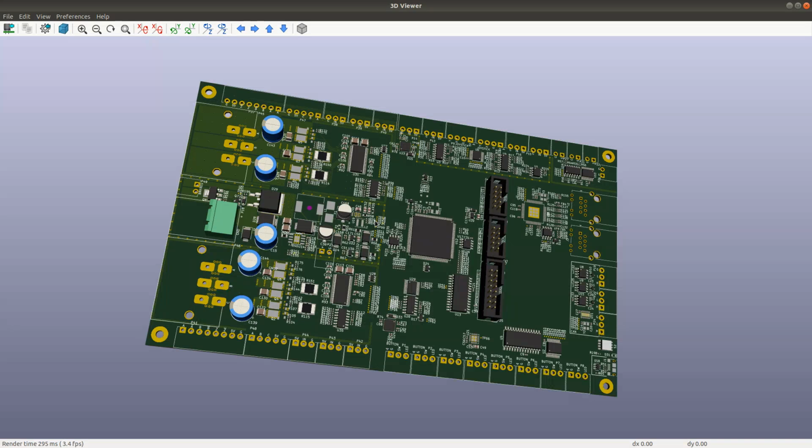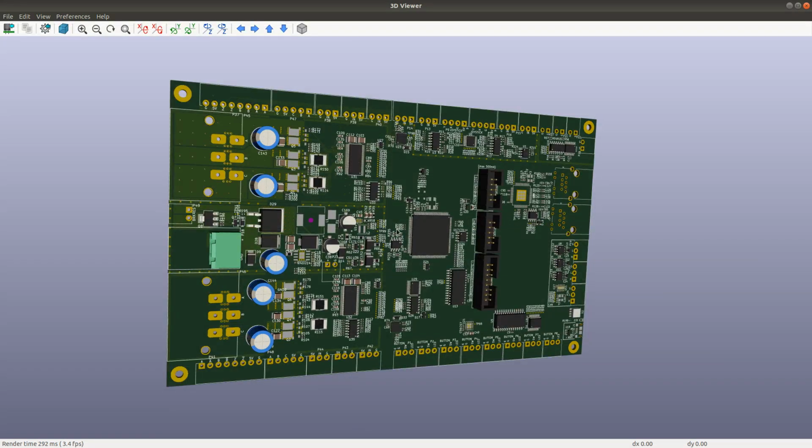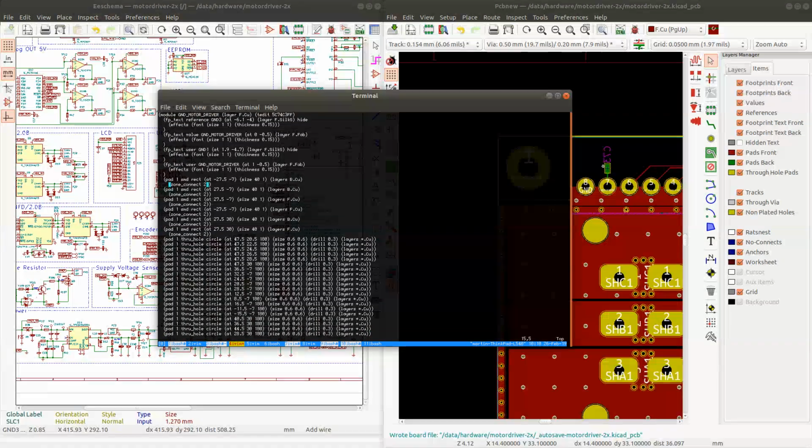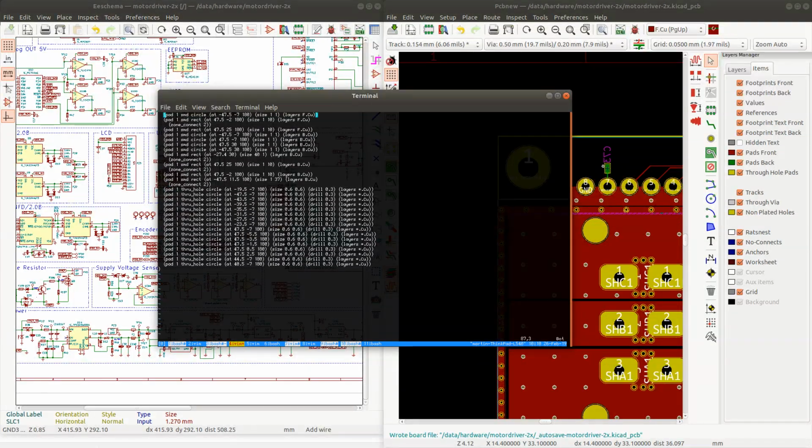And now I have to do the same thing for all of the other footprints that have vias that are still uncovered. Let's see. And the sizes are going to be 0.6 and 0.3 millimeter hole. And also, I want to make sure that I have zone connect set to 2 on all of them.